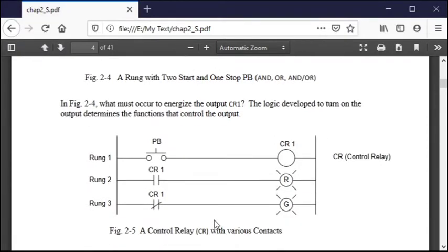Here is a circuit that you're going to see here, and you're going to see it later on in this chapter. You're going to see this as a push button, and that push button turns on a light. It turns on when you push this button. This light turns on. That contact closes. This is not a capacitor. This is a contact off of this relay. It's referenced off of CR1, and there it is. That's a contact off of that relay.